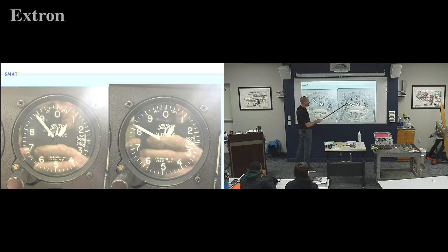Roughly 1,000, so down to the hundreds, 800, and I'm double checking, it's probably not 10, 20, 30, 40, 50, so 20, 40, 60, 80, 100, so 820. So, this is actually taken of a SMAT aircraft sitting here in Ionia with the Kollsman window set to the correct setting for the day. So I went over there, I don't think I called Ionia, I just said, I'm getting ready to go fly. So I'm going to spin it to 820, and that's what AWOS would have been reading me on that day. If I set it to 299 or 2, it would have said I was up here, different numbers.